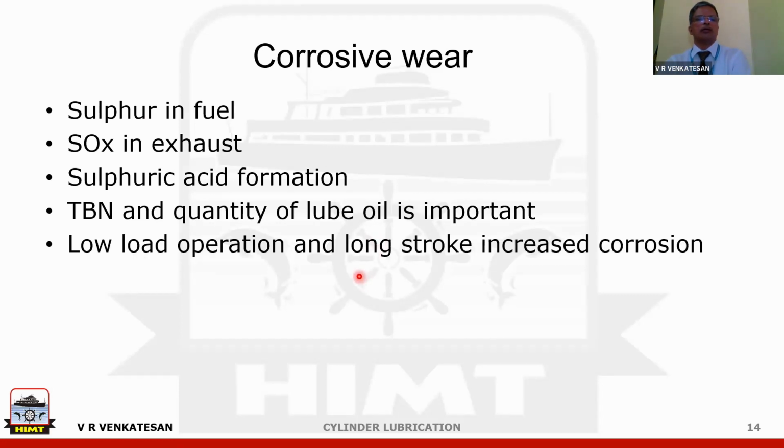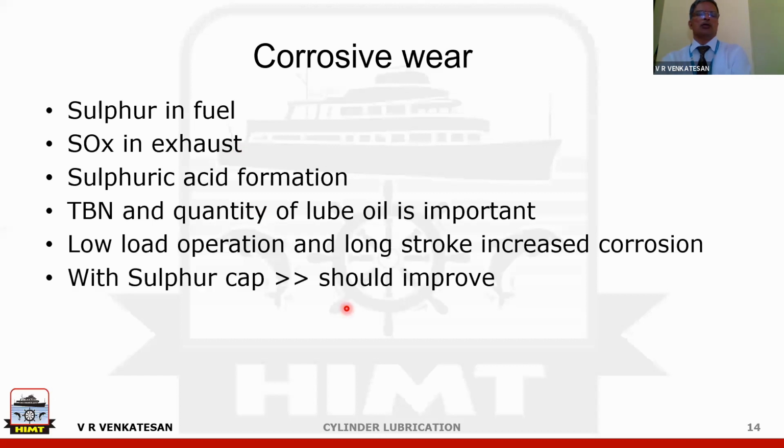Now, the issue that is happening is, if you run your engine on low load, and as the piston stroke is increasing more and more, large portions of the liner are at cold temperature. So this low temperature of the liner will result in more corrosive wear. Fortunately, to a large extent, this problem will be reducing, because in whichever vessel they are opting for low sulfur fuel, this corrosive wear should come down.